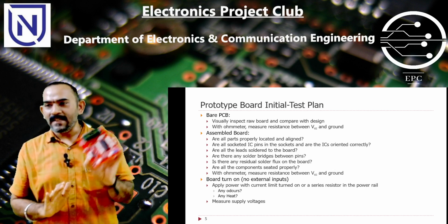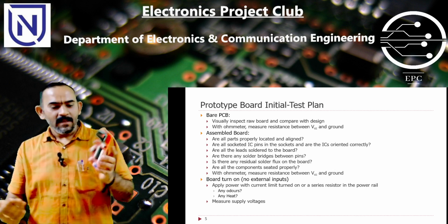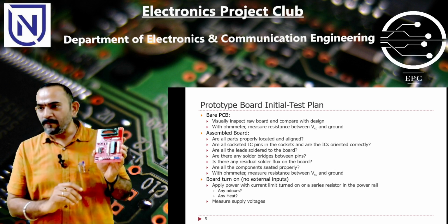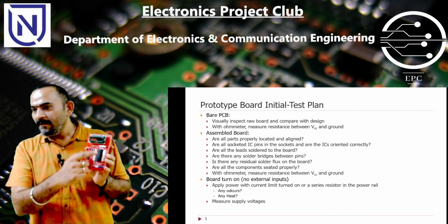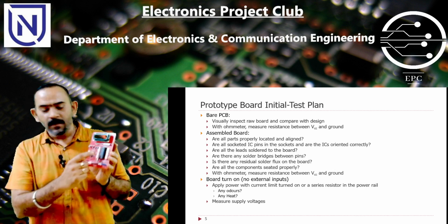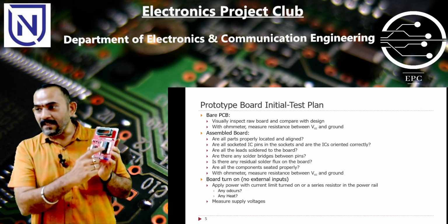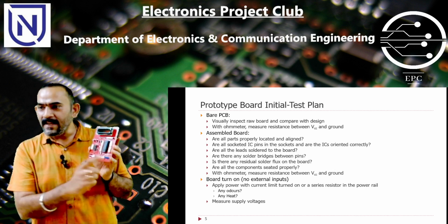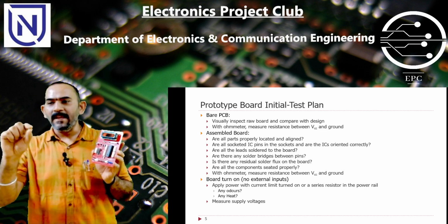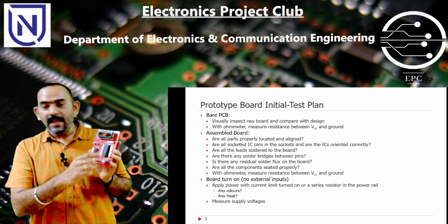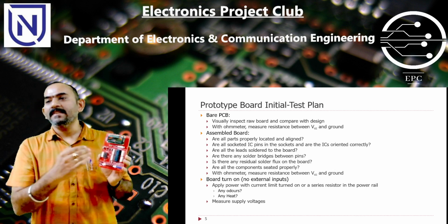So you have completely tested this board. Now once this much is done, next stage, if it is embedded, for example this is a microcontroller board, to continue further testing I need the help of software team, where they can write a small piece of code to light this LED. Then I can check whether the trace from this point to this LED is working fine or not. I run a small piece of code which will blink the LED. Then I know this works, connection also is working fine. So this is the process.